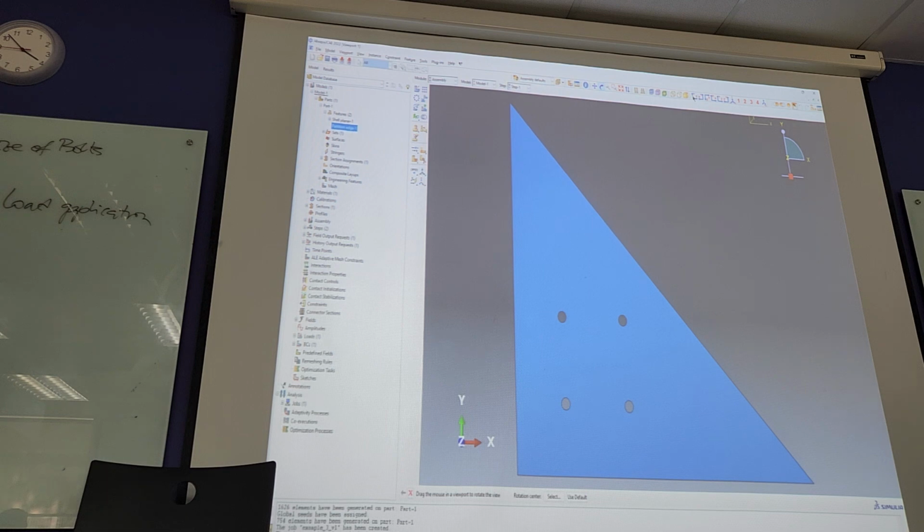When I draw the outset, the part that goes on the shell, I increase the section, why do I need to give it as a shell? Shell in part creation is sort of a CAD feature, but in property it deals with whether it's solid or shell as Abaqus features. So they are not the same. Although they are all the same, that's what confuses us.